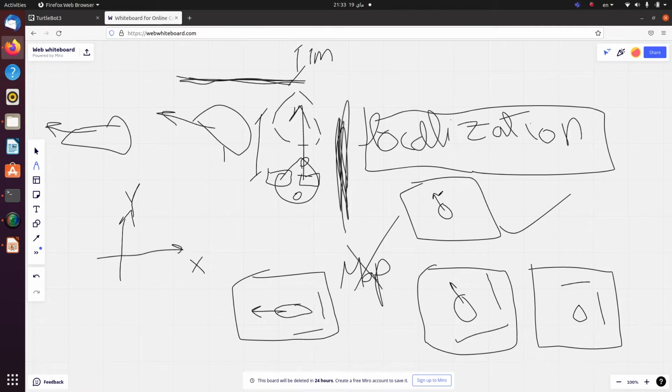So I got all the robot poses to overlap together into a single entity here, and then I get a very strong drawing, or a very strong belief in the location of the obstacles. So too many obstacles are overlapped together, and then I know for sure that the global map has the obstacles, for example, here. All right, so this is what mapping is all about, and it assumes that localization is covered.